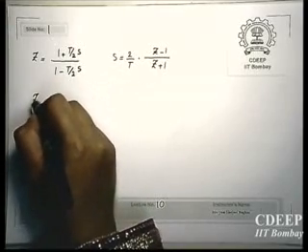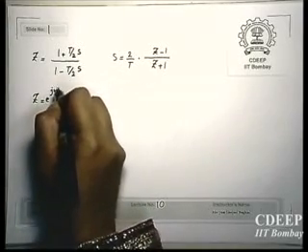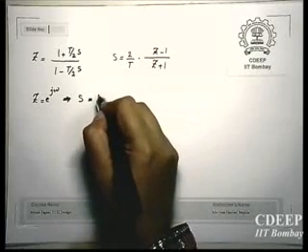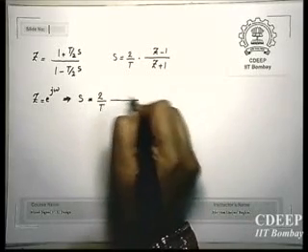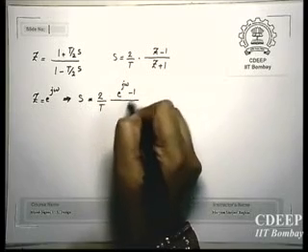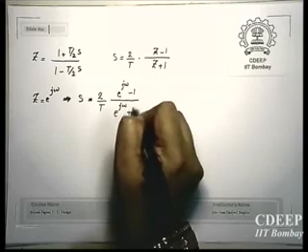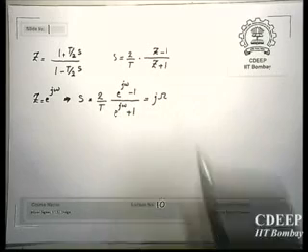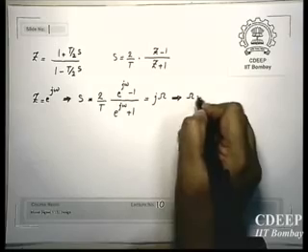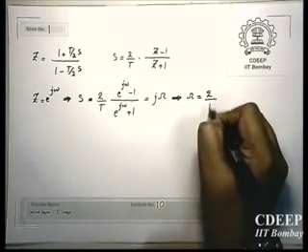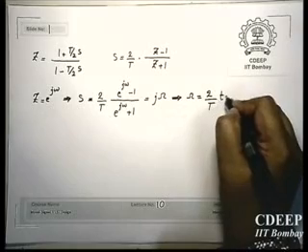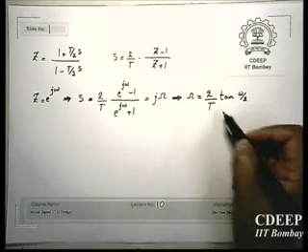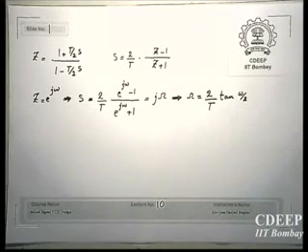By replacing z is equal to e to the power j omega, you will get s is equal to 2 by T times (e to the power j omega minus 1) upon (e to the power j omega plus 1), which is equal to j capital omega. And therefore from here, when you do the same thing we did yesterday, you can derive capital omega is 2 by T tan omega by 2. Just this coefficient or scaling factor of 2 by T appears.